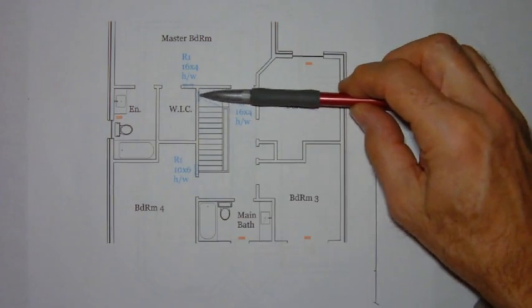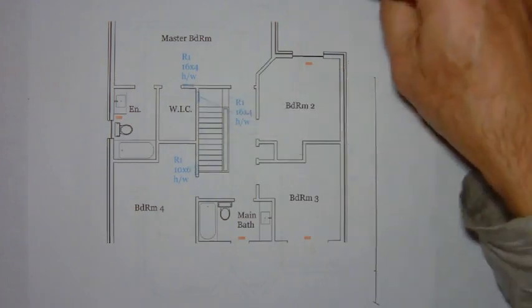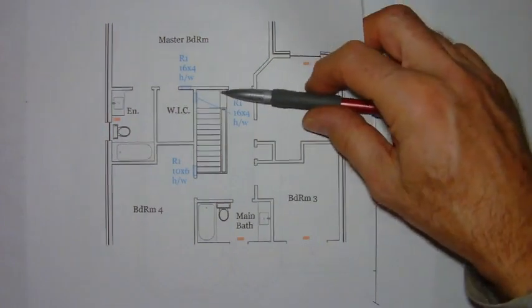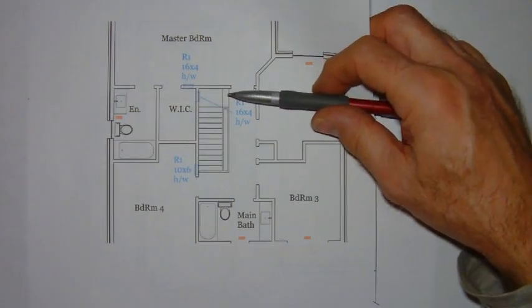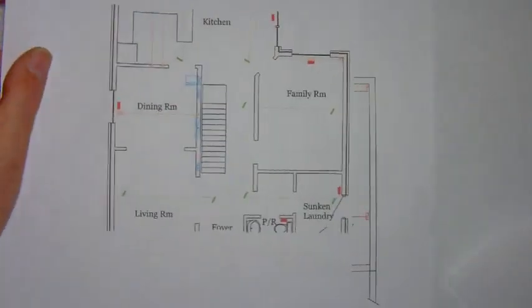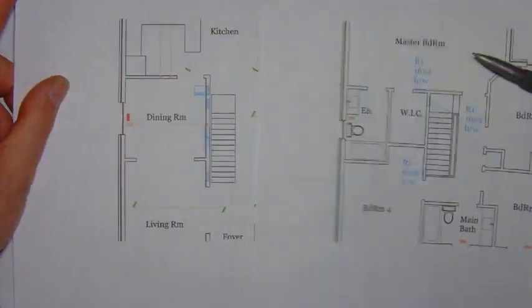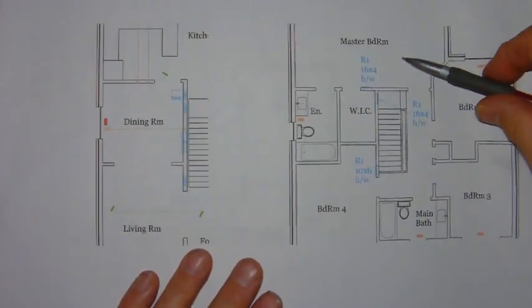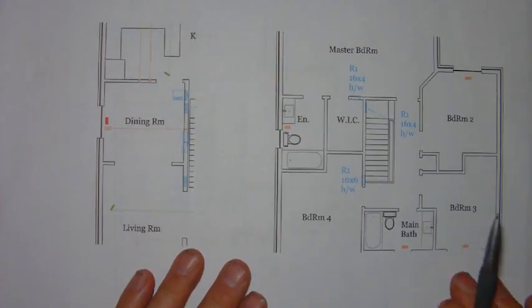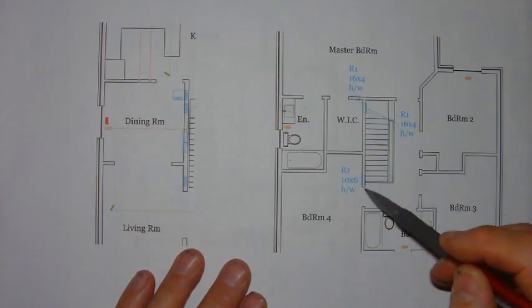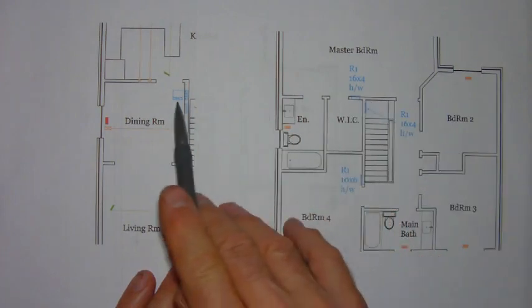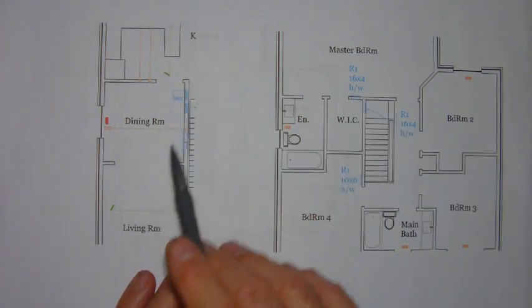So once you've decided on these locations, you have to verify that in fact these locations have corresponding joist spaces on the first floor to help us get the air down to the basement. So the easiest way to do this is to simply compare the location that you've selected here on the second floor and transfer it into the first floor.